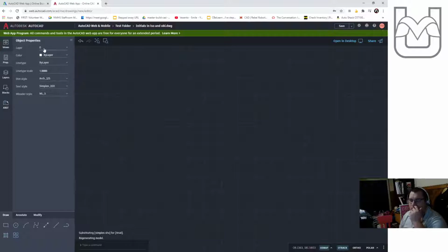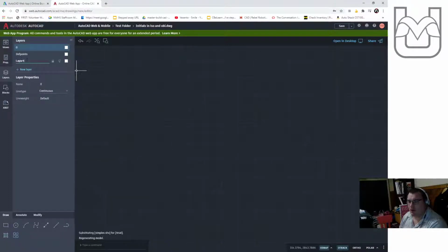Okay, we have a properties tab. This is the one that I always use, kind of hanging out on the side of my work pane, and it'll tell us all of the important things about our various lines and pieces of the drawing. We have our layers, and I'm going to mess with this right now and create a new layer and call it my drawing layer, because that's what we've been doing for a lot of these initial drawings when we learn some techniques. Okay, it gives us the option to show it and lock it if we want to. It also lets us change its color. I'm going to turn it yellow so that you can see it on the screen here, and so that we can start drawing. Also line weight, we can actually change whether it's dashed or dotted, if we need to do hidden lines.